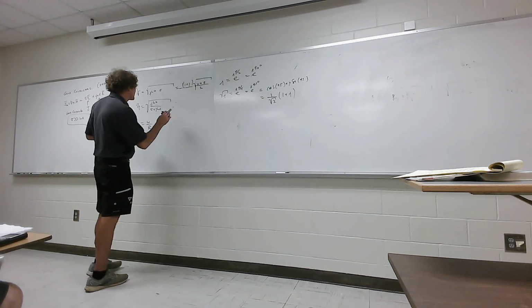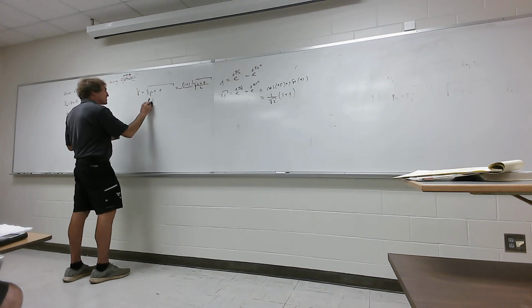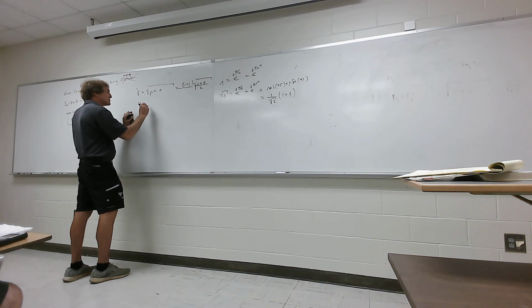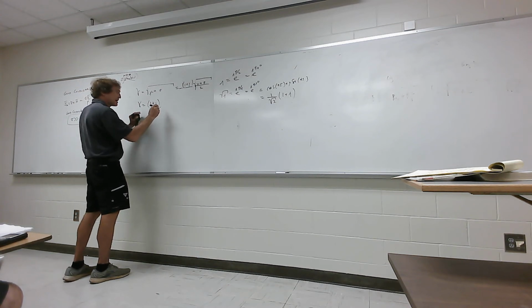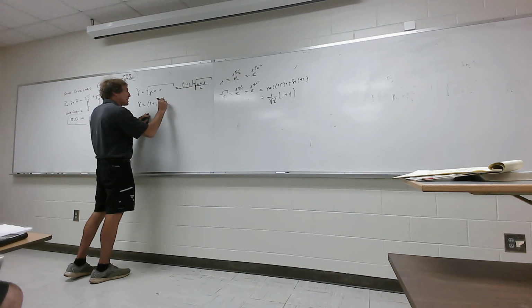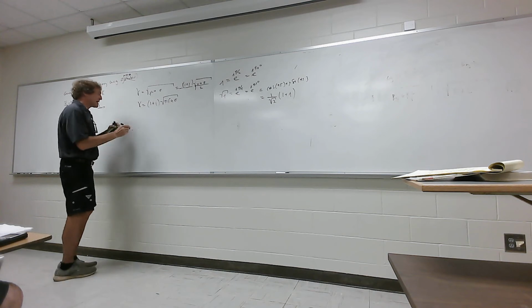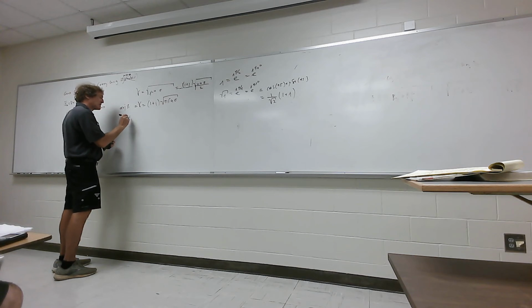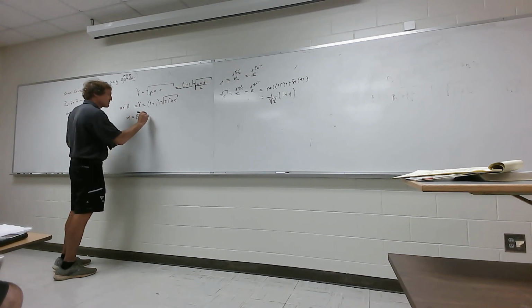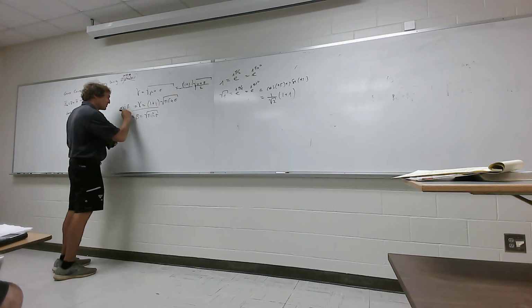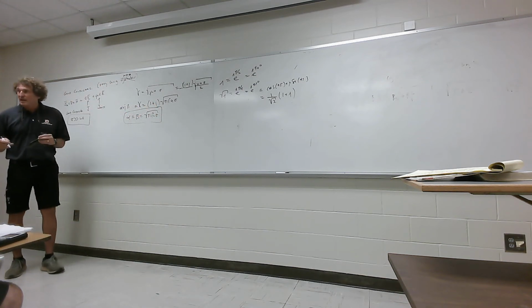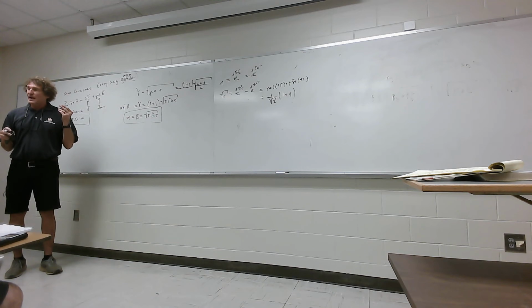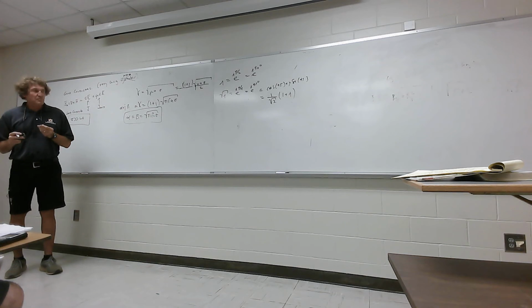So what you end up getting is this. You get that gamma is equal to 1 plus J times the square root of pi F mu sigma. And it means this, since gamma is equal to alpha plus J beta, that alpha is equal to beta is equal to the square root of pi F mu sigma when you talk about a good conductor. Beta and alpha have the same exact value. You got that, everyone? Now that's important.